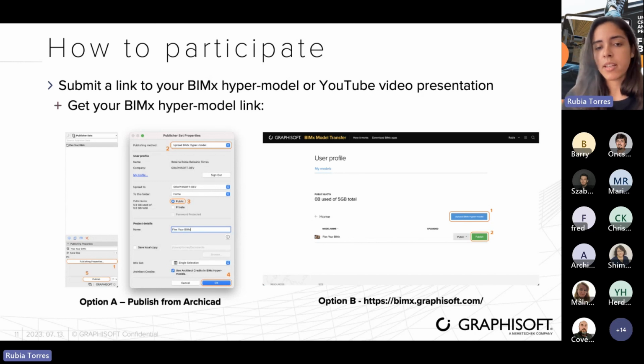And if you opt for sharing the link to the BIMx hypermodel, you have two ways of getting this URL. So you can publish the BIMx file directly from Archicad to our BIMx model transfer site. So you set the publisher set and the publishing method to upload to BIMx to upload the BIMx hypermodel. Make sure to set the visibility to public. And optionally, you can set the Archicad credits. It's always a good practice. And then you click OK, and the BIMx hypermodel will be uploaded to the site, and you can copy the URL.